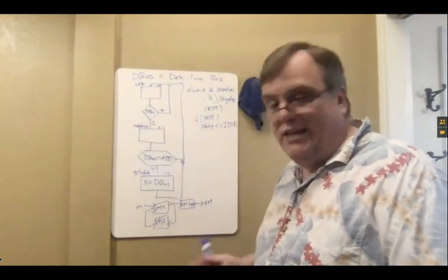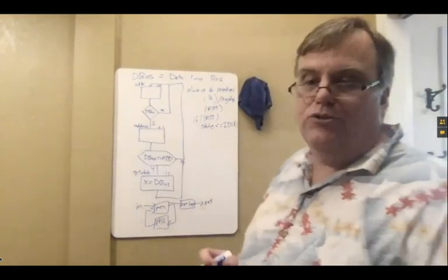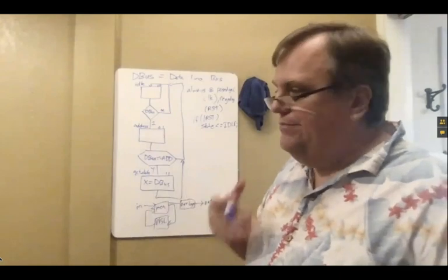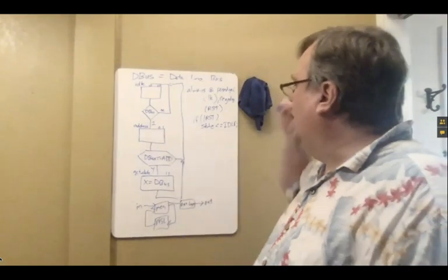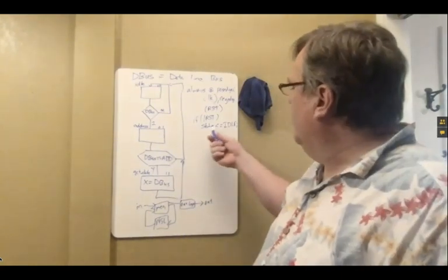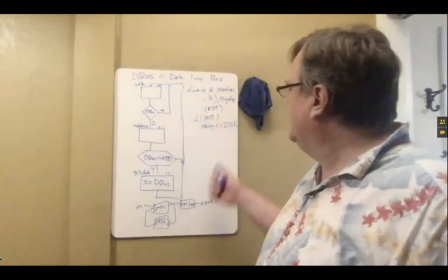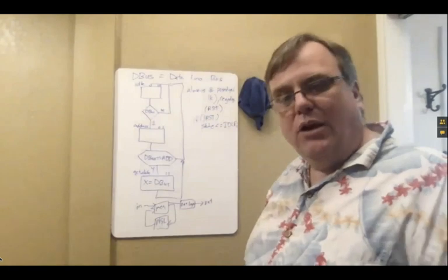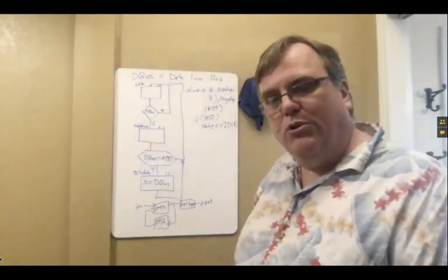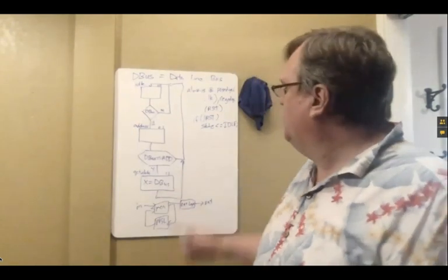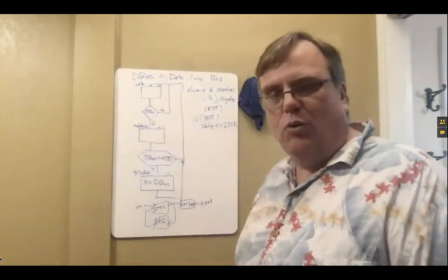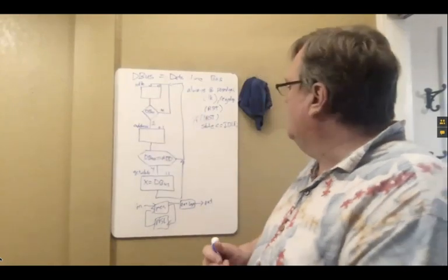But for instance, Intel doesn't start their computers at address 0. So, go figure. Sometimes people don't use 0, so it is a little safer to do this for the reset. On a reset, go to the idle state. That way, also, when the computer starts up, you can send that reset call through and you know it's now in the idle wait state.